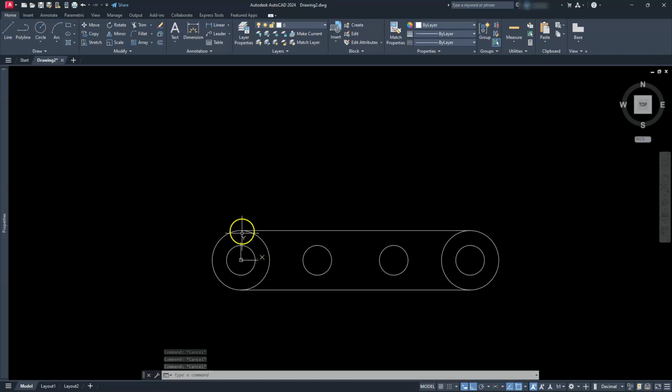Next, I need to go ahead and tell it to create this next circle. This circle is located somewhere in this area. Now, I do know the distance of it. It's going to be a -5 from here. And then I need to go up a distance of 52.5. So I'm just going to choose circle, center radius. Now it's going to ask me what do I want to put that. Since I do know where my 0, 0 is, I can type in -5.